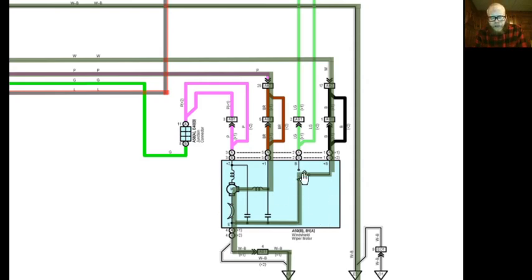Down here, there's this weird switch. This is the park mechanism. So when you are wiping your windows off when it's raining, nobody wants to have to time it perfectly so that when the wipers are down, you hit off right now, or the wiper's going to get stuck in the middle of my windshield and make it hard to see. So they add this mechanism so that when the wipers are down, the switch would be in this position, right? Because all diagrams are drawn with vehicles in their at-rest position.